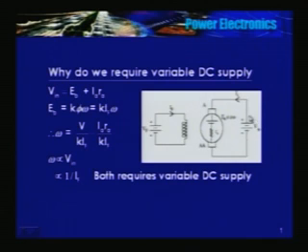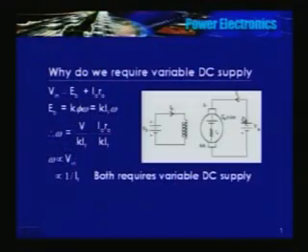So I can have a semi-controlled or half controlled bridge here. Let's see, as the power rating increases, what modification do I need to make in the power circuit. One of the options is, in both the cases, I can have a semi-controlled bridge. You may say, why not use a half wave controlled rectification using one thyristor?